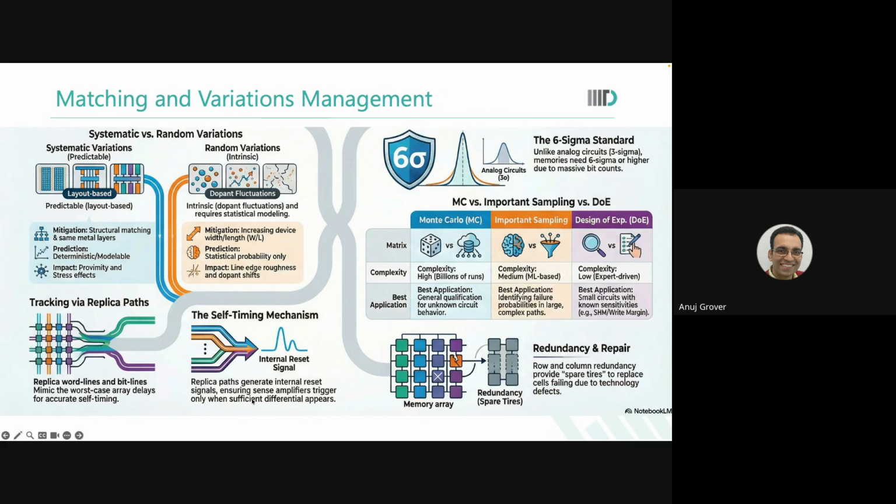So what is done is, in between any two dies, there is a space of a few millimeters, or part of a millimeter, depending on how good your slicing, laser cutting material is. But whatever it is, it is far larger than a few nanometers. It has to be, because wherever you cut, a different kind of stress will happen. So any active device should be far away from those cuts, at least a few tens to hundreds of microns away. That is a requirement.